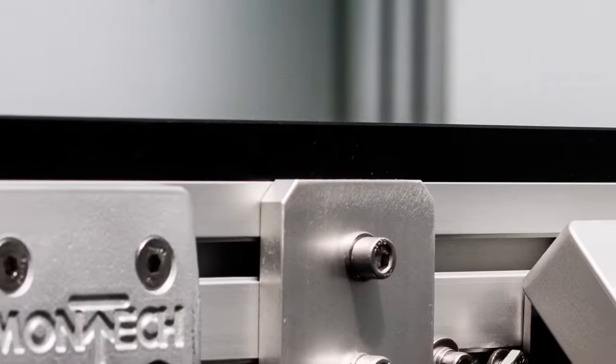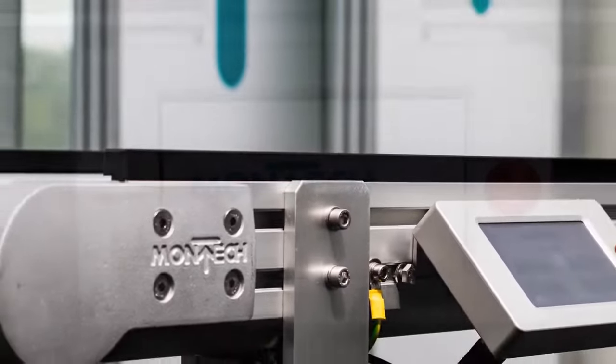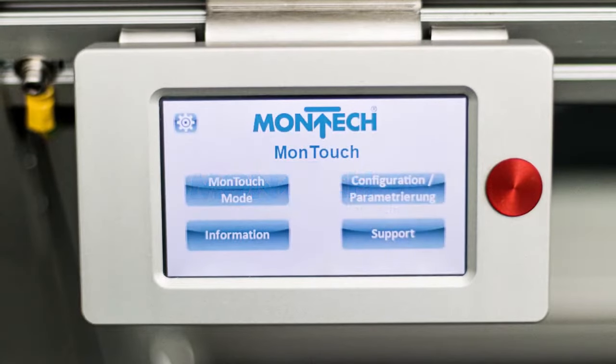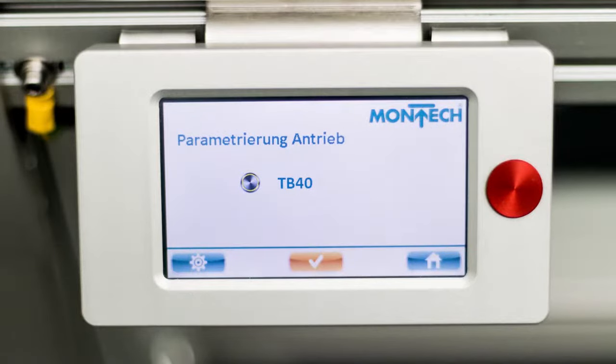When you connect the MonTouch controller to your TB40 conveyor, the initialization screen will appear on the display. Depending on the saved operation mode of the drive, the user interface displays MonTouch operation or parameterization. If this is not displayed, please check the connections of the cables and the power supply unit.